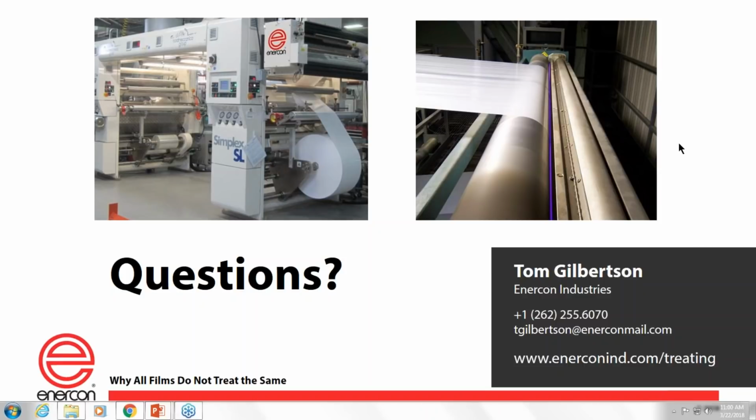And why it's used is because it has a lot of benefit relative to treating all kinds of film. It has dyne level benefit, meaning that we get some bump in dyne level for the same given unit of power versus a bare roll treater. It has some film handling benefit relative to treating some thin gauge film. And on top of it all, it can treat conductive materials. And so it really is the best of all particular corona treaters wrapped up into one.